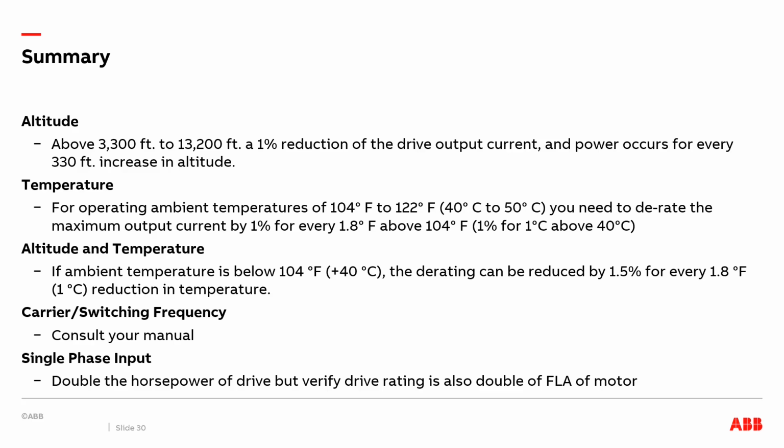When we talk about carrier and switching frequency, I would say always consult your manual. There's a lot of different ways that the derating can affect a drive because it varies so much between voltage, frame size, and horsepowers. So again, consult your manual.